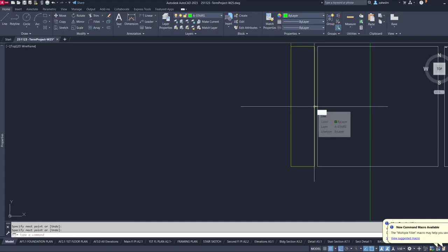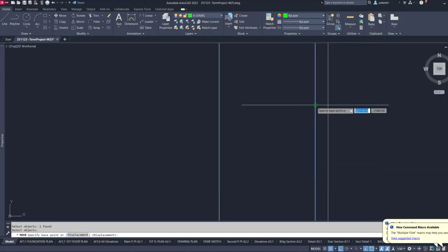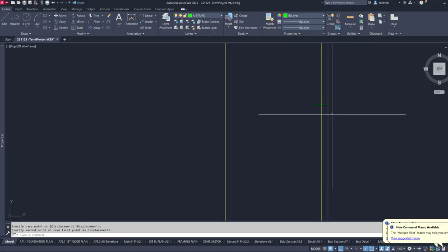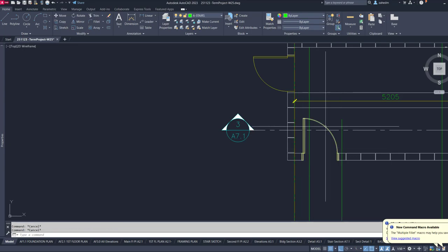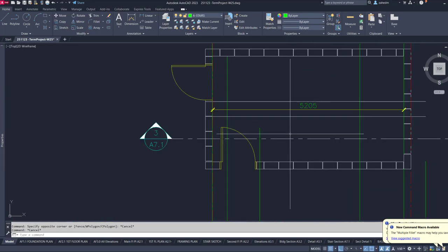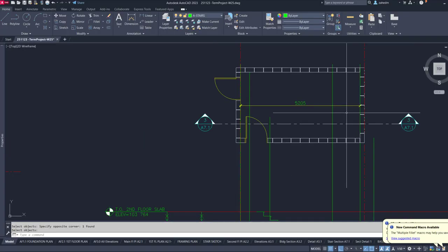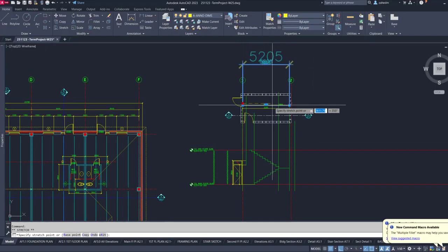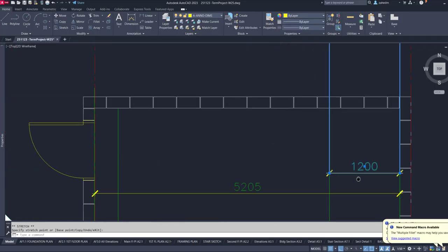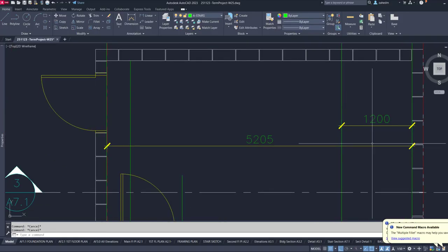I use the manufacturer's website to get the door sizes. That's why it has become like that. The doors and everything else are based on the real numbers taken from the manufacturers, and this is a dynamic block, as you see. All right, what I'm going to do, I'm going to remove these two lines. As you know, we did this landing for 1200. Let me just move it up and then use this dimension. See, this is 1200 now. That's exactly what we want.